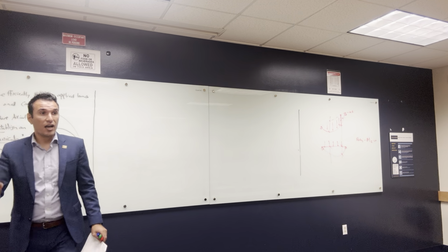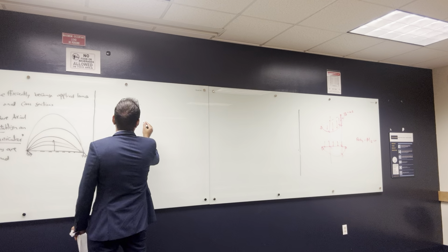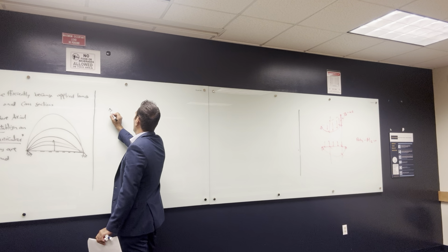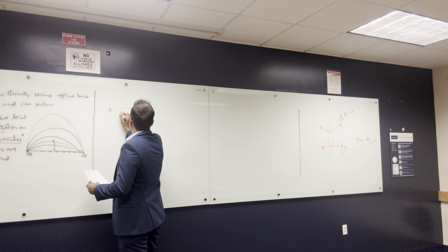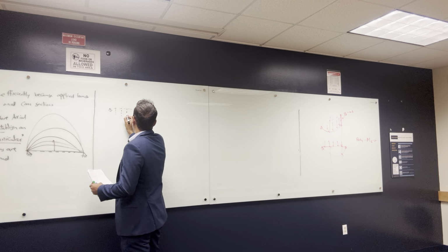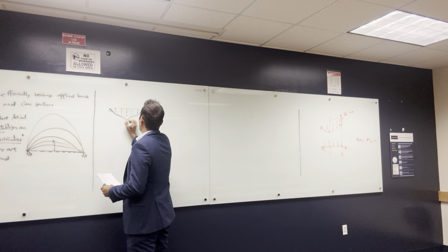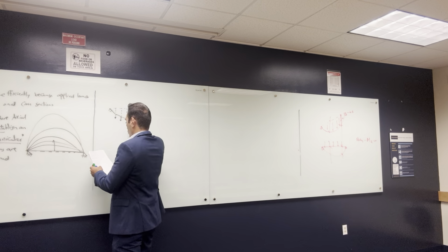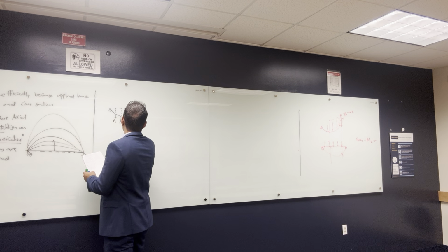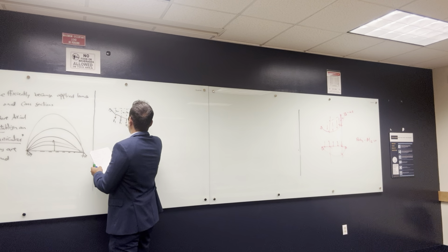All right, so if you want an arch to be funicular, it has to be the same shape as a cable. Let's say you have a cable like this, and let's split it into equal pieces. This is the cable, and it has loads P1, P2, P3, P4, P5. And this is H1, H2, H3, H4, H5.